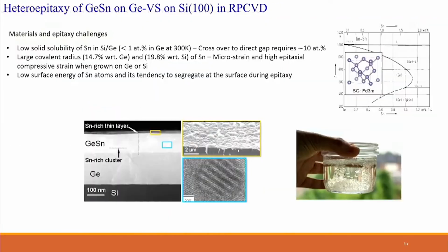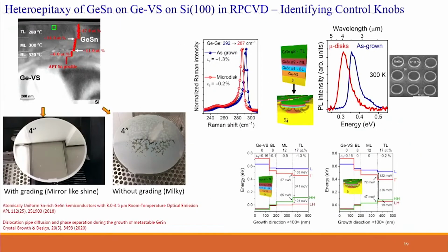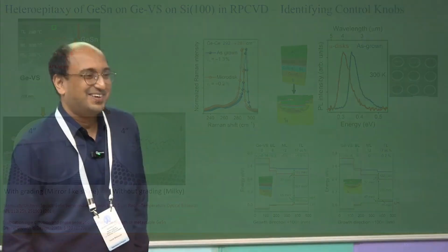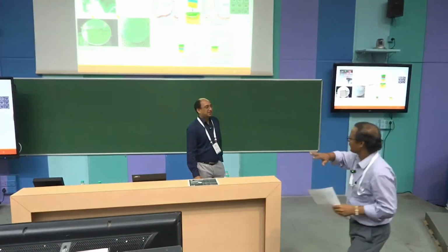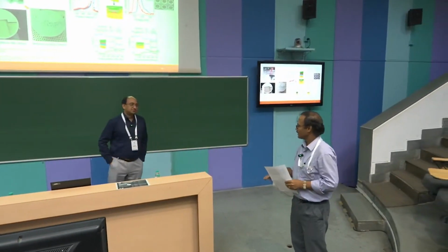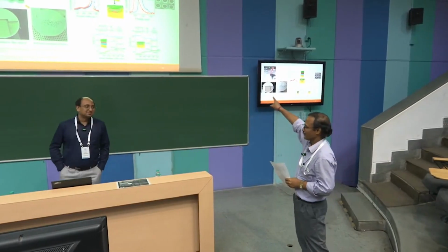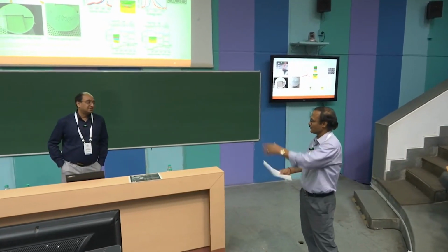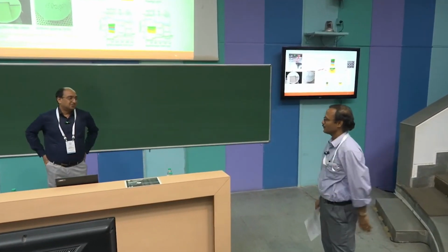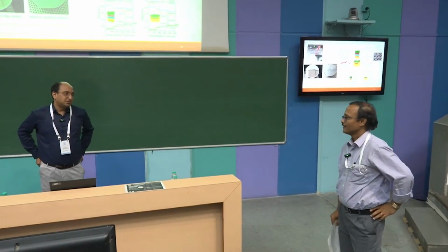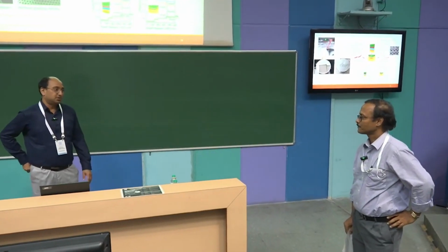Even when we are bumping concentrations like this, you can typically think of this as also a kind of homo-interface. It can nucleate there as well. So it's surfactant-mediated epitaxy. Usually in the MBE community, they use it to glide those dislocations in a different order on the surface. In MOCVD or CVD, you also use no surfactant? No, we use hydrogen. Hydrogen plays an analogous role to surfactants.